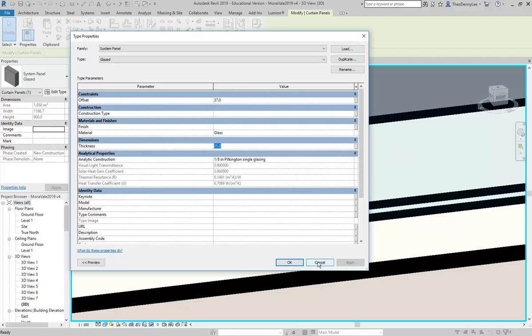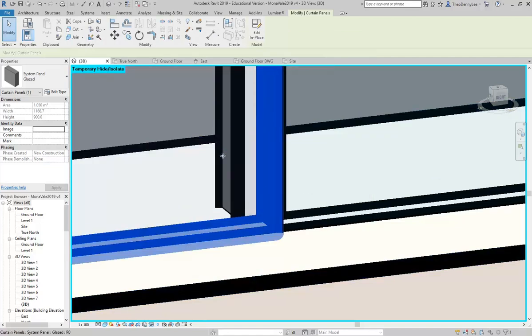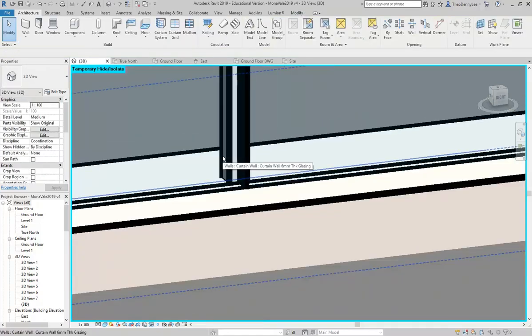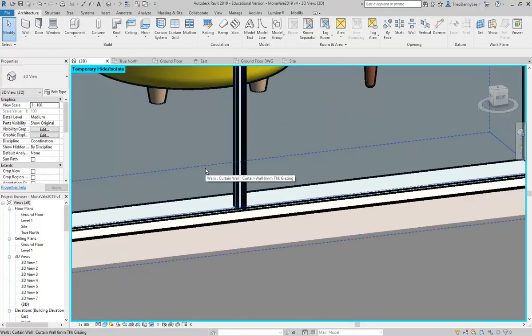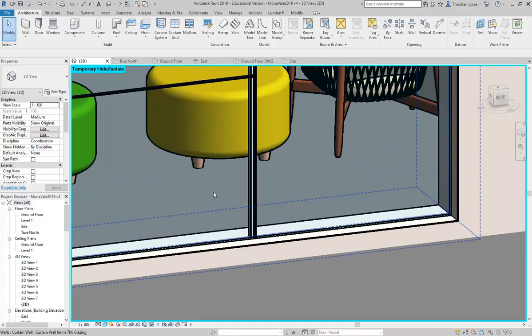Now, do you know how thick glass is in real life? Yeah, but there are some standards. Yeah, 3 is actually not far off. So old glass in older buildings, it was only a few mil thick, and you'll see that in picture frames, things like that, they use the same sort of glass, and it's a nice trick if you ever need to replace glass in an old window or something like that. Often you need to go and find something like a picture frame to get that really thin glass. But it's not very safe, so I'm not going to recommend to use that for windows, but for internal fanlights